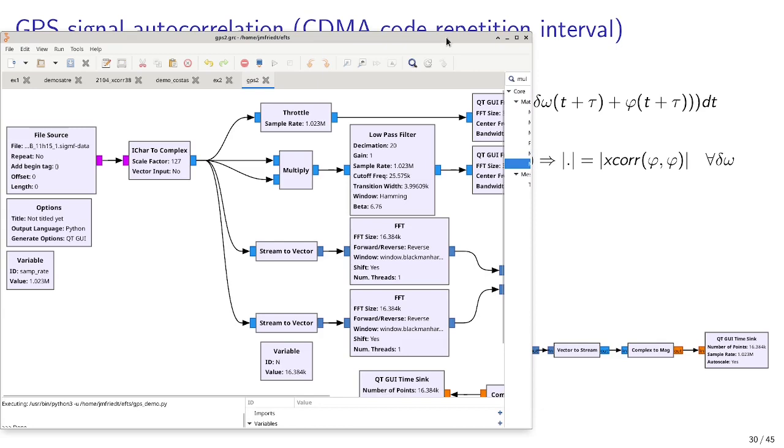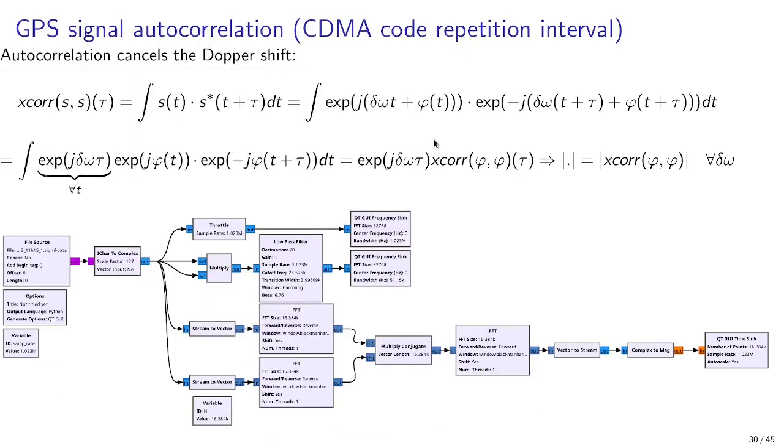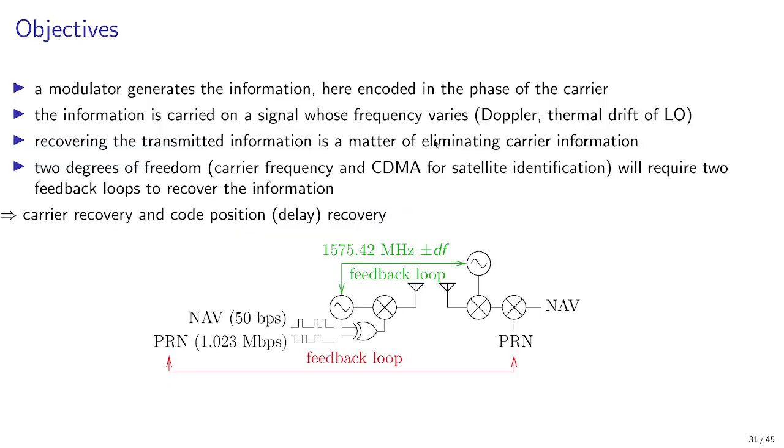We now conclude by correlating with the code sequence of the Gold codes. However, a remaining challenge is that by correlating a frequency offset signal, we are unable to accumulate energy since the mean value of a sine wave is 0, and if some frequency shift remains, then the correlation with the Gold code sequence will not accumulate energy.